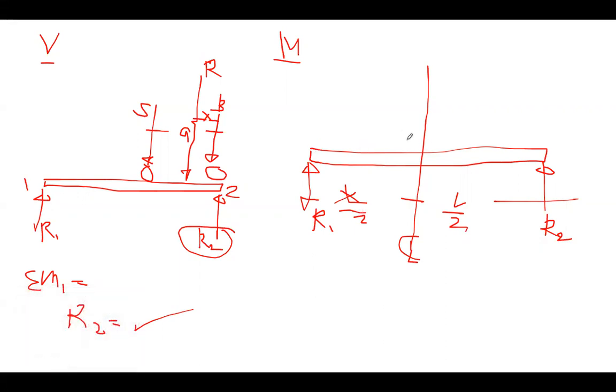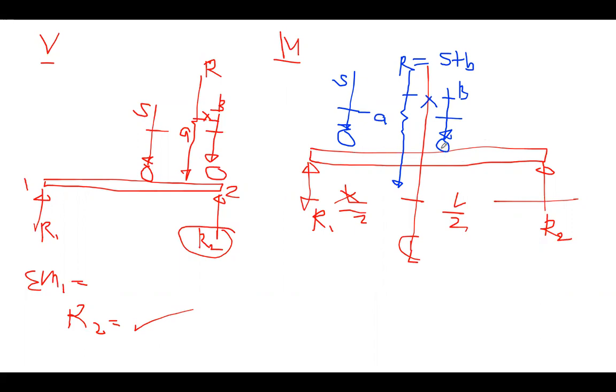So, what you need to do is to place the center between R and B coinciding with the center line of the beam. If this is the bigger load, here is supposedly the resultant load. And here is the small wheel load. Okay? If this distance is equal to A, this is equal to X. R is equal to S plus B. Okay? Maximum moment is just located here.